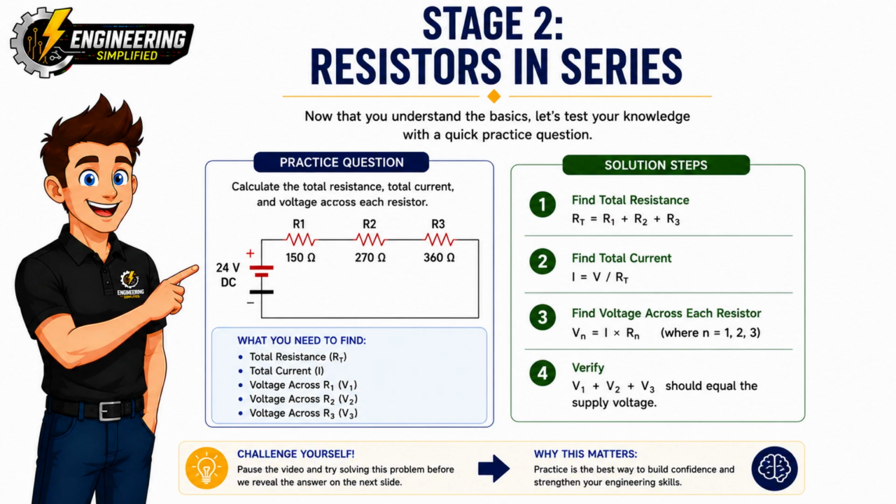First, add all of the resistor values together to find the total resistance. Next, use Ohm's law to calculate the total current flowing through the circuit. Then, calculate the voltage drop across each resistor by multiplying the current by the resistance of that resistor. Finally, check your answer by adding all of the individual voltage drops together. If your calculations are correct, they should equal the 24-volt supply.